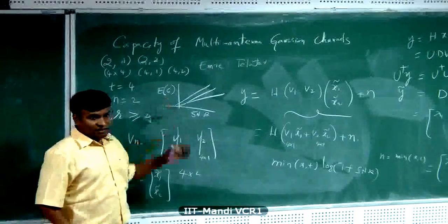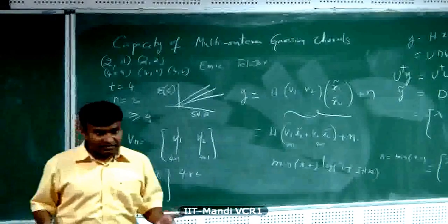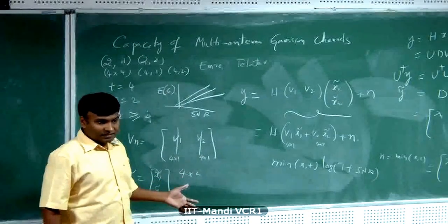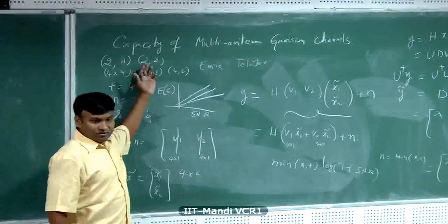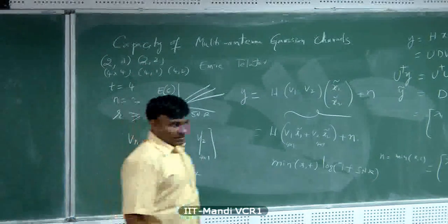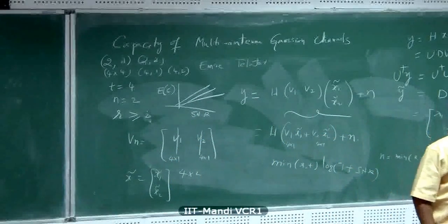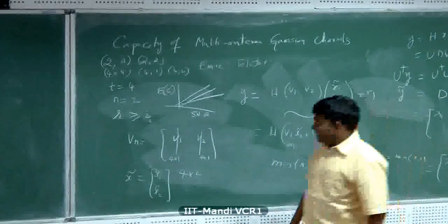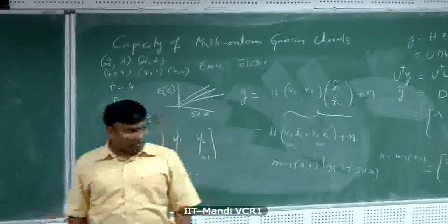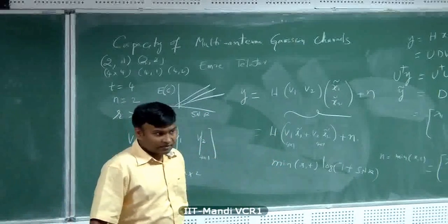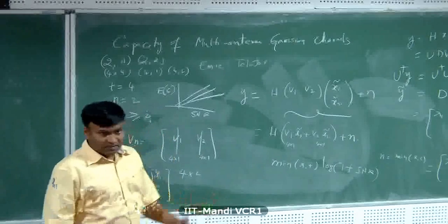And how do you calculate this? Well, simulate a number of H matrices and average it, and then you can see the various trade-offs. This is easy to do. There is no bit rate simulation involved. Generate different H matrices using IID complex Gaussian entries, and calculate the capacity using the framework we developed. Okay? Through simulation, you can see what's going on.